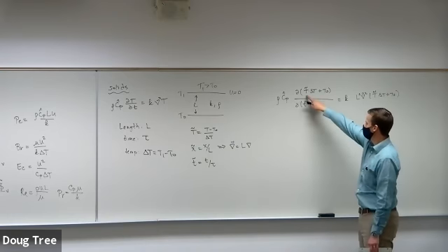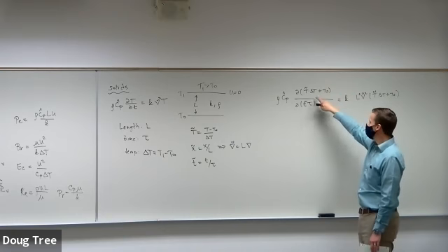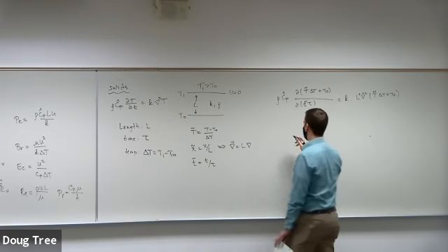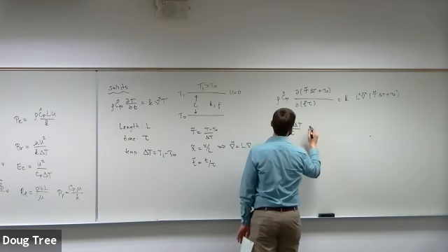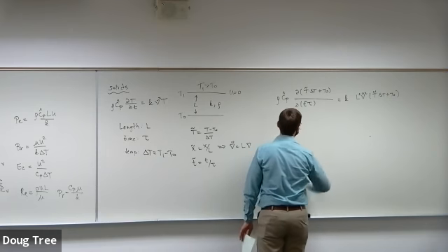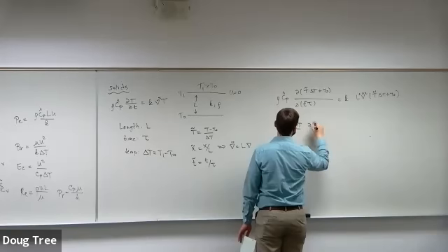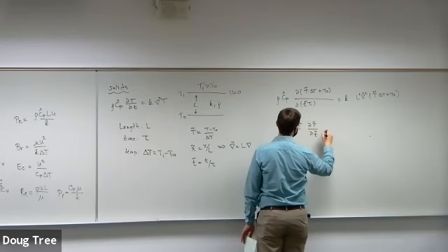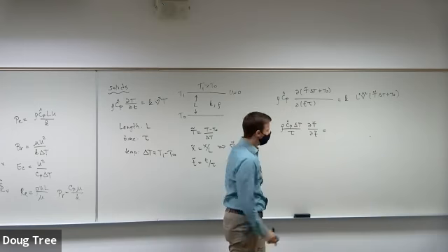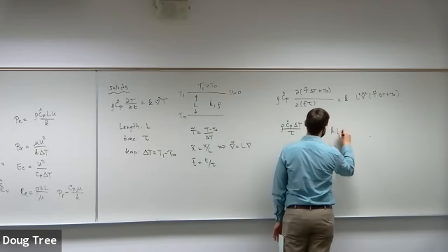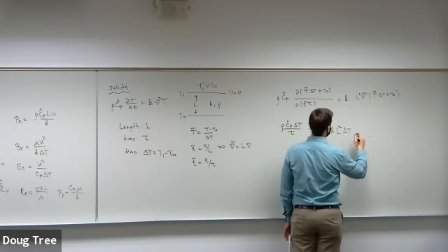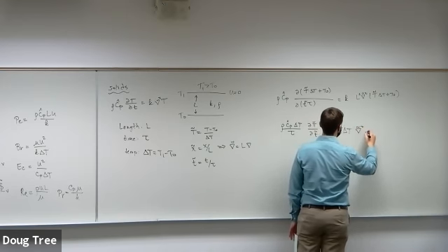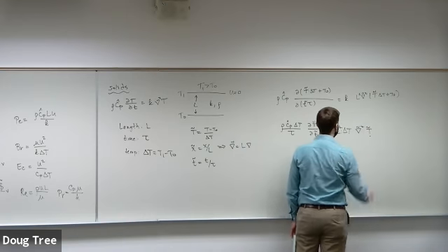Okay, so copy those guys up there. This derivative will take the derivative of t naught, that'll be 0. Delta t comes out and the tau comes out. So I get rho c sub p hat delta t divided by tau. Don't forget the important stuff. d t tilde d little t tilde is equal to, and on the other side, I have a k over L squared, and then a delta t comes out of my grad squared t tilde.